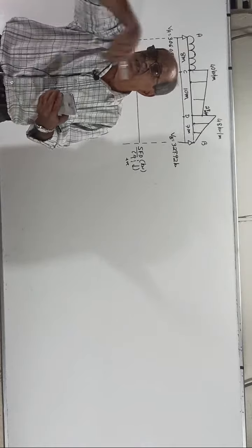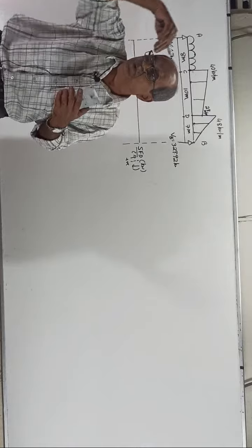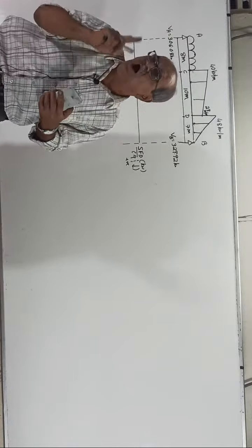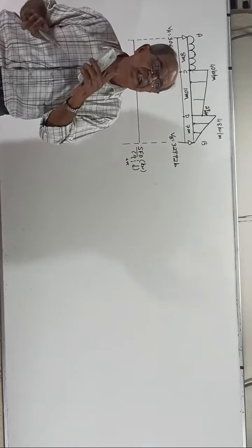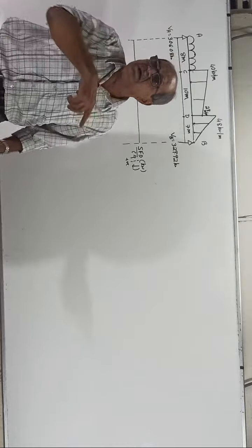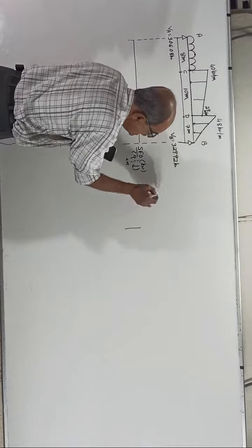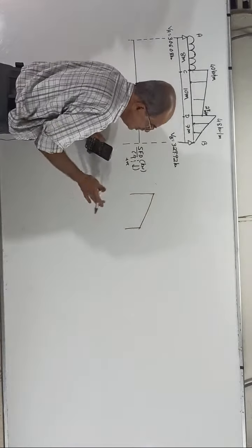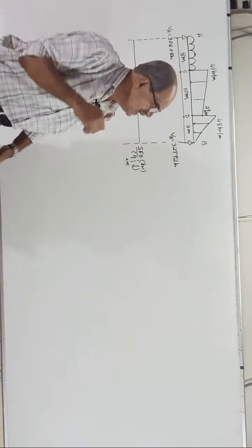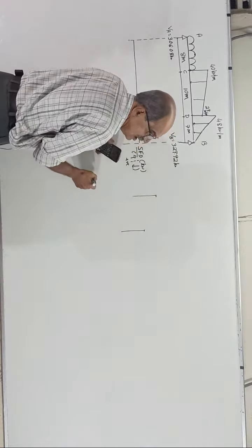Point load means suddenly there. If it is UDL, linearly go down. If UVL is there, go down not linearly but with parabolic variation, second degree. See, if it is UDL, there is no confusion. Why? Linear. Suppose I want to join this one to this one, linear. Join. You don't have to decide slope, nothing.